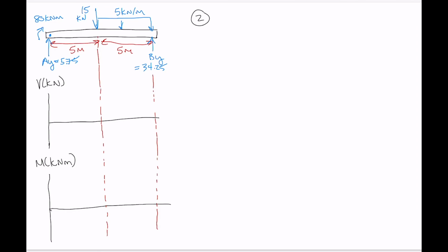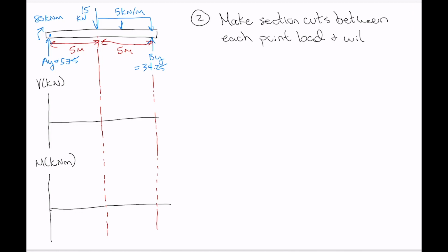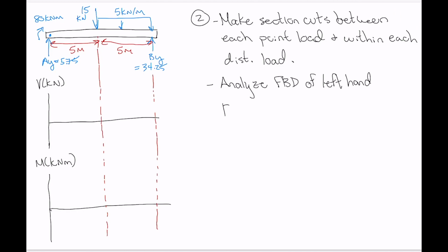But the important thing here is that we make section cuts between each point load and within each distributed load, and then we analyze the free body diagram of the left-hand portion of the beam,